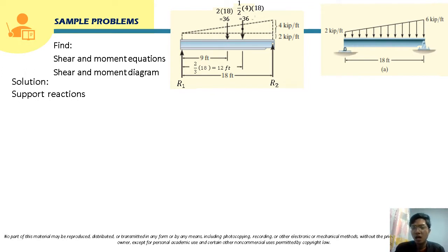But in this case, in our beam, there's no horizontal loading here. So the horizontal reaction here will just be 0. So there's only a vertical reaction here. So this will be the reaction for the hinge. Okay. And then, class, since we have here a trapezoidal loading, to solve this we can convert it into its equivalent point load. We can divide this trapezoidal load into a rectangle, so this will be the rectangle, and then into a triangle.